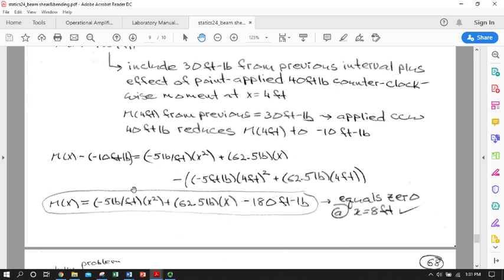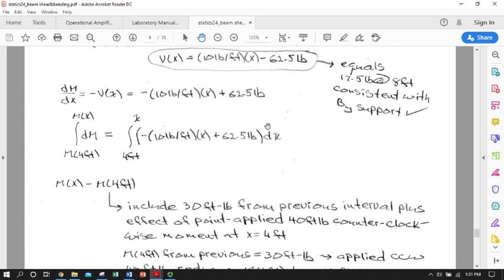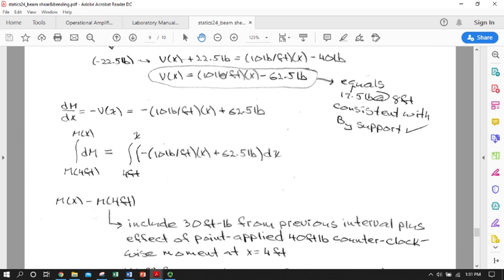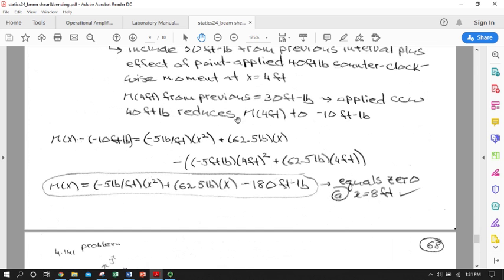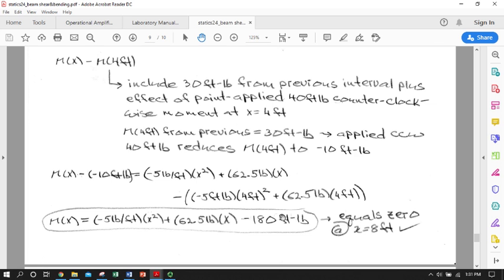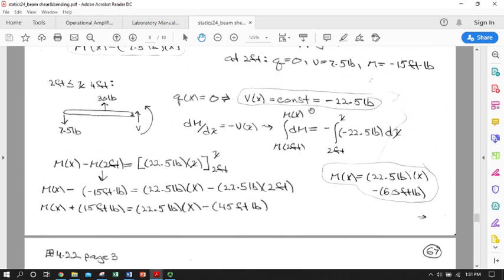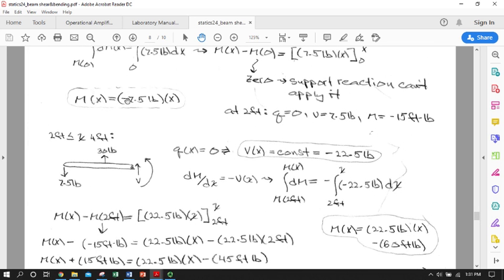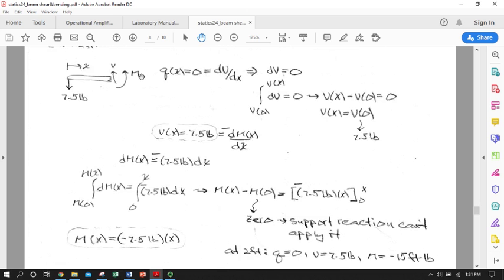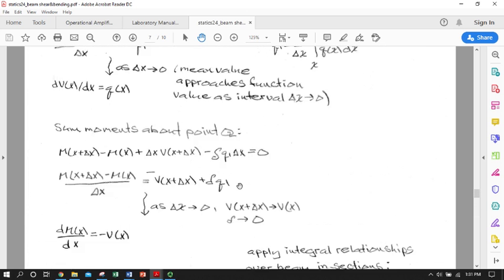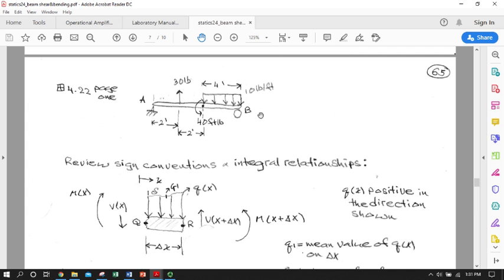Concave down, parabolic moment, probably coming up from a negative number and reaching an exact 0 point at 8 feet. And in that same section we have shear, linearly related to x. So we could, if we wanted, use this expression over its interval of applicability, and then these ones, and we could find out when M and V were maxima over the entire original beam and find our maxima points.